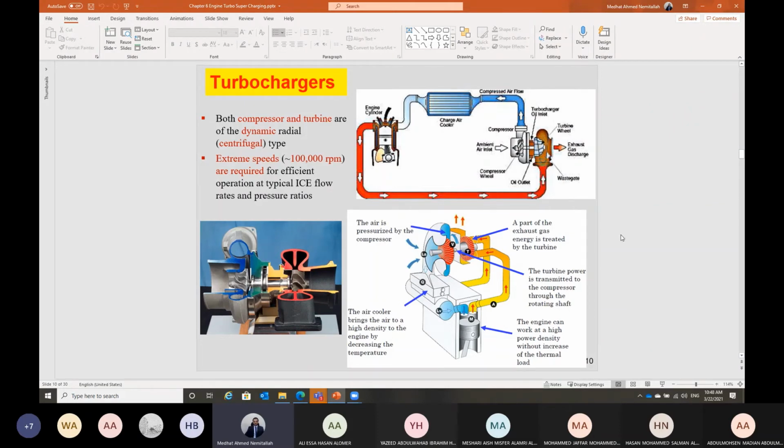This is regarding the supercharger, in which we have a compressor that takes the power from the crankshaft. And we said this is one of the drawbacks of the supercharger, that it takes part of the power output of the engine, so it will be less efficient. But the supercharger has one main advantage: because it takes the power from the engine, it can drive better boosting conditions at lower RPM compared to the turbocharger.